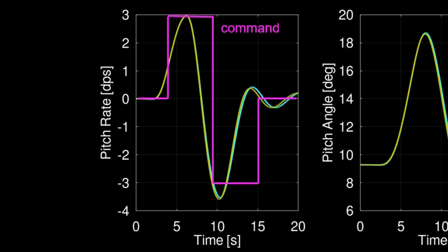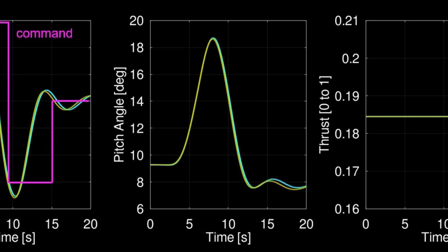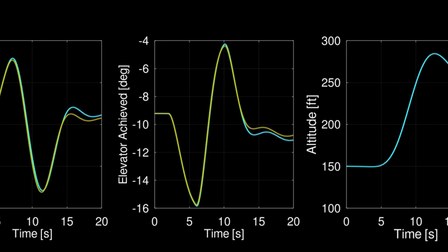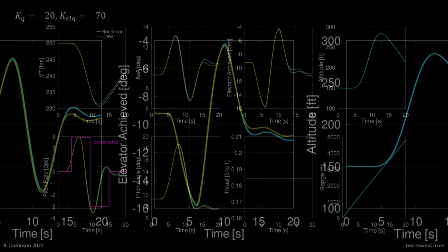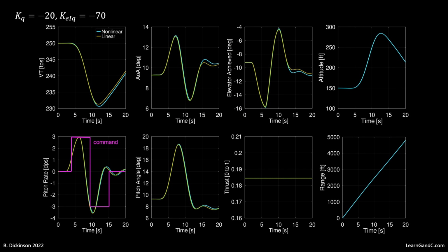A doublet is now commanded, simulating a pull-push-release on the control column. We observe pitch up, then pitch down motion, peaking at roughly 10 degrees above the trimmed pitch angle. We can also see a gradual elevator response to the commanded pitch action. The symmetric push-pull of the doublet, while applying constant thrust, in the end leaves us slightly off the original trim condition.